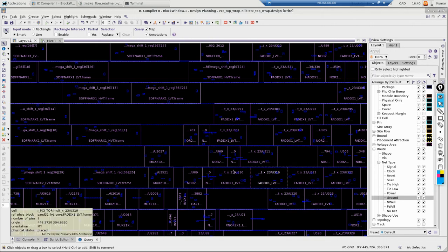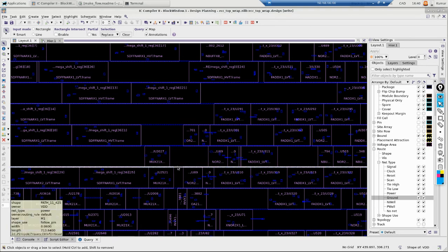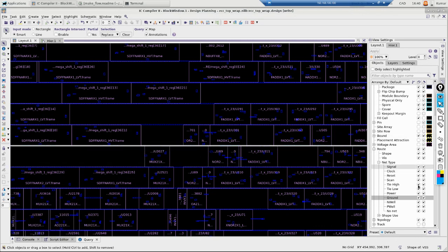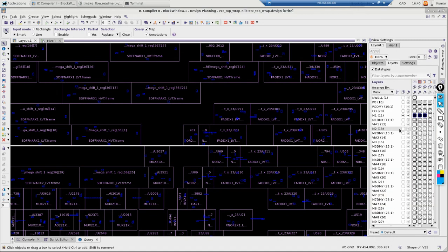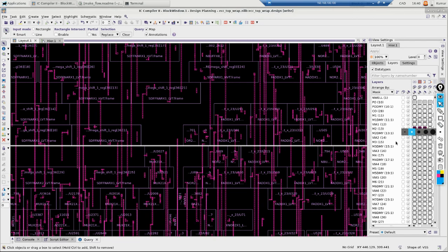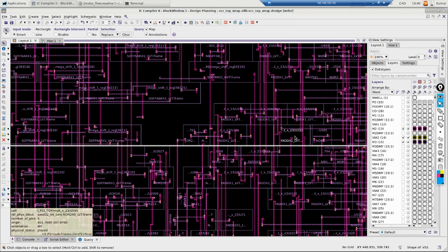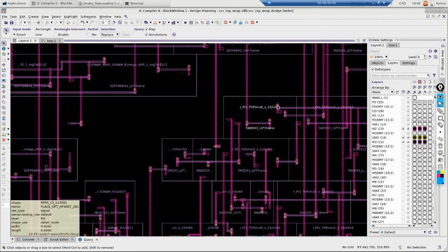So if you look at your standard cell rails, they would be the M1, first layer. So in this process, we have M1 which is horizontal. Now let's take a look at your layer 2. Do you see any horizontal routing here? Do you see any M2 which is horizontal?